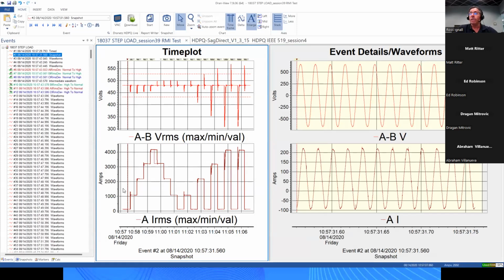And you can see here's the step test. Here's the current that we're seeing. And I honed in on the AB voltage and the A current, just to make things simpler here, but you'll see similar results on B and C. And you can see I stepped to 25. Well, I didn't, our customer stepped to 25%. And here is the change in voltage, 50%, 75%, 100%. And the same thing when they step down.